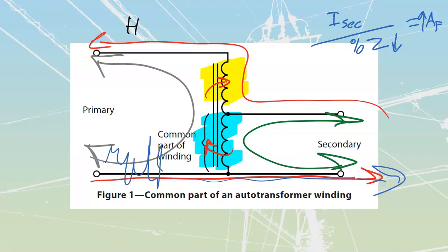Normally transformers are really good at filtering them, because a transformer is simply two inductors, and two inductors are going to act as a really good filter, cutting off a lot of these really spiky, dirty little bits of waveform. But now we're able to conduct them straight across. So we do get more issues across like that.